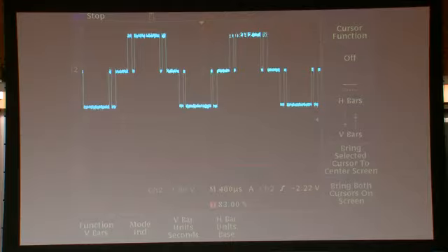You will notice that the higher harmonics are getting higher in magnitude, but that's okay, because we care about the lower harmonics more, because it's easier to get rid of the higher harmonics. We'll need smaller filter components or smaller devices for applications. That's all.